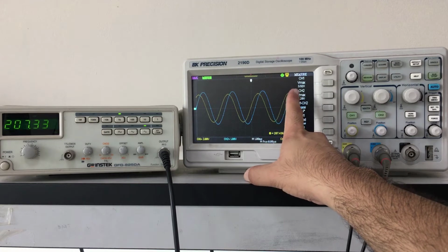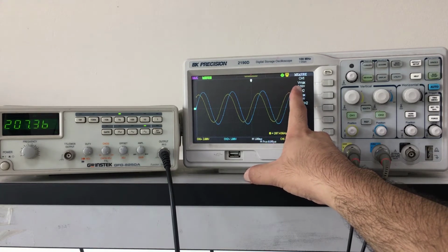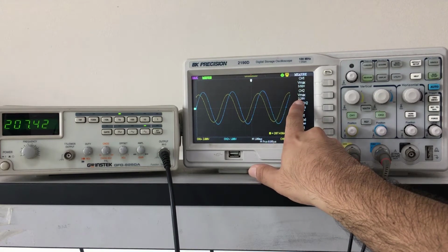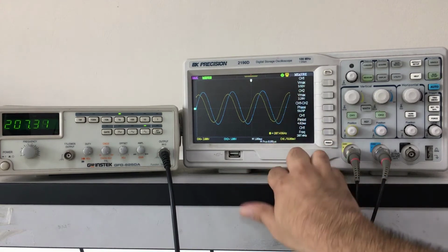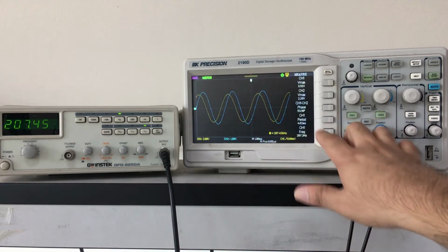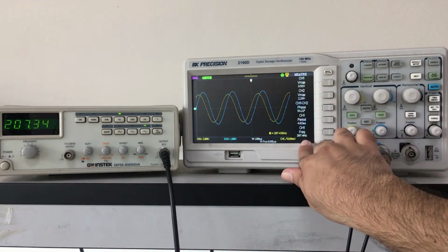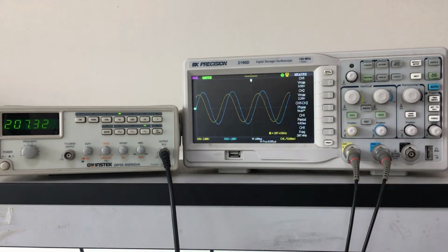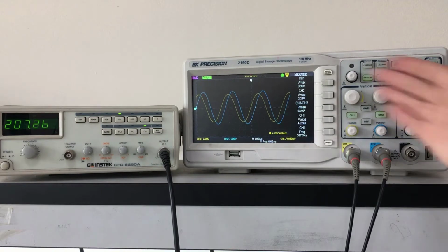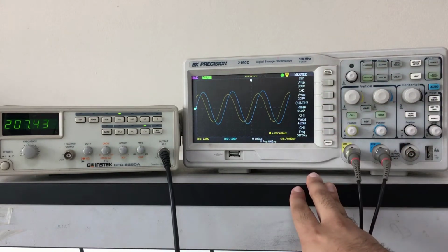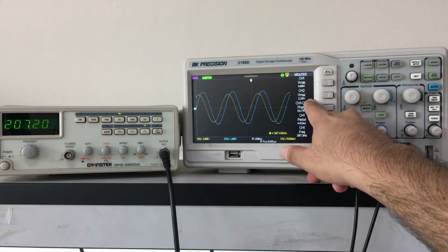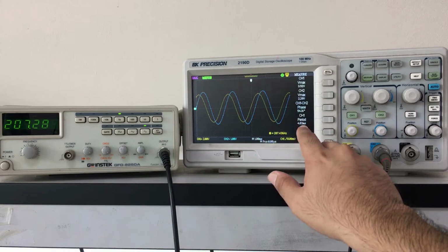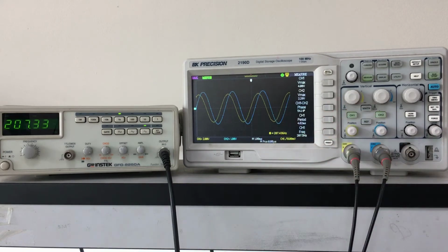So channel 1, which is connected to node A, is giving us the input frequency. Channel 1 Vmax is 3.92. A brief reminder that these are the values being shown by default, because the previous use of the oscilloscope had these settings. When you turn on the oscilloscope, you may not find these values like this. You can change any value that you want by pressing the appropriate button.